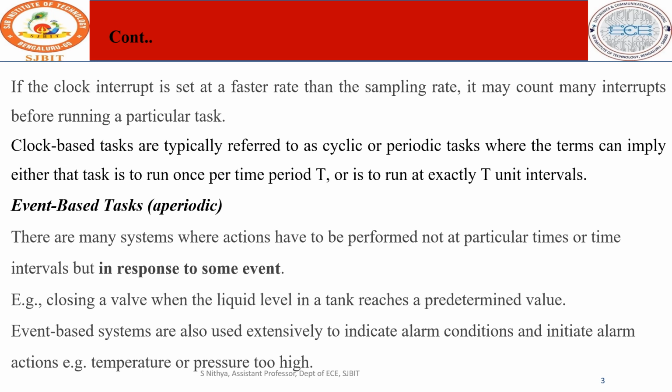Okay, so there are many systems where the actions have to be performed not at particular times or time intervals, but in response to some event. The events occur at non-deterministic intervals, and event based tasks are frequently referred to as aperiodic tasks. It does not happen in equal periods of time, and that kind of task is called an aperiodic task. Such tasks may have deadlines,